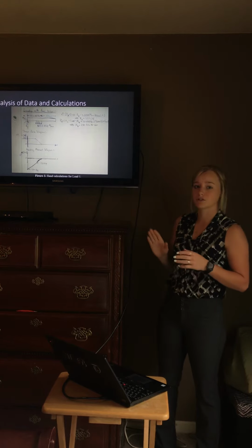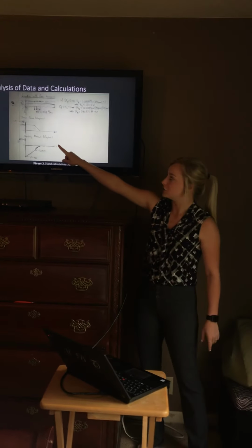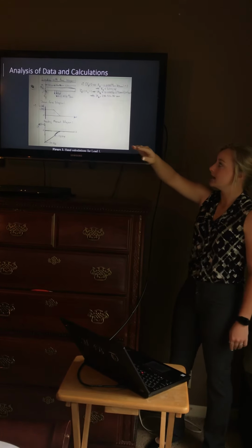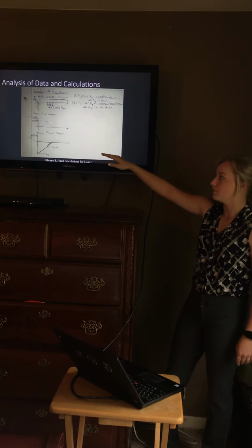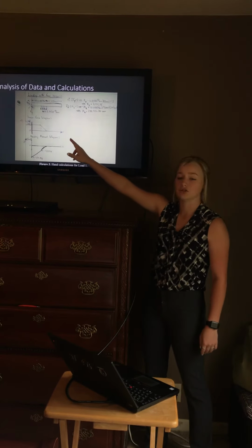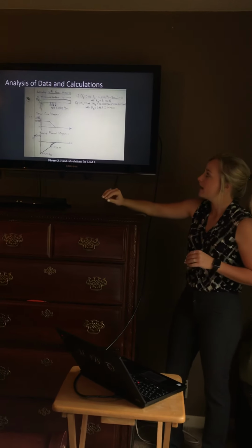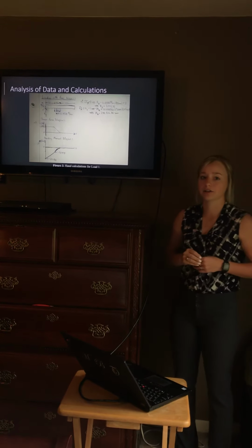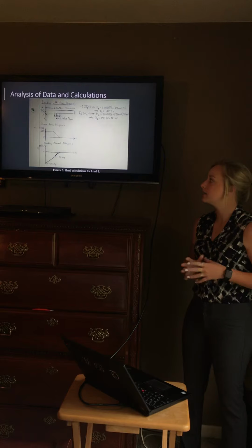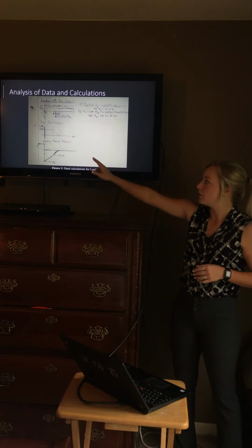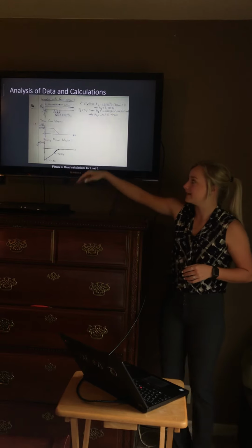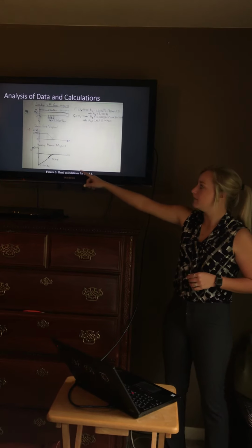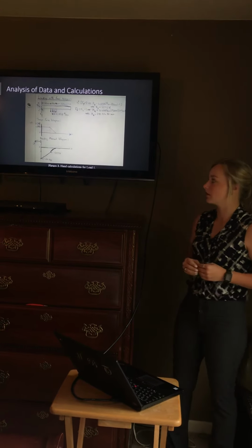From this, it was used to draw the shear force diagram. Since we had a reaction force in the y direction acting upwards, the shear force diagram starts at 1.1772 in the positive direction. There's no more force applied until we reach the distributed load, so that remains level. And then once we reach the distributed load, it decreases linearly back to the 0 point. And then from there, we calculated the bending moment diagram by taking the area under the shear force diagram, and that's how we get our maximum bending moment and how much it decreases along the beam.